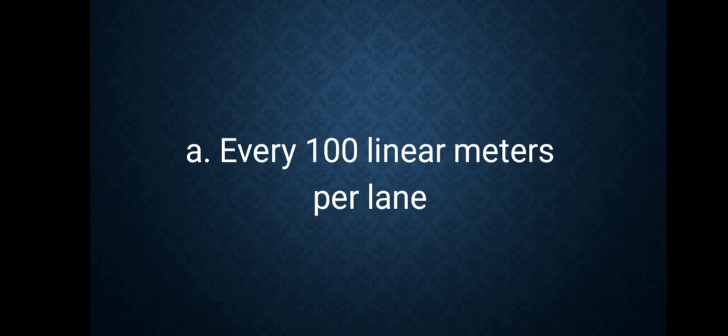So according na sa book san volume to san DPWH standard specification volume, if no core samples were taken during the day's operation, core samples shall be taken from the completed pavement for every 100 lm per lane. So the contractor shall supply and furnish new material to backfill boreholes left by the samples taken.